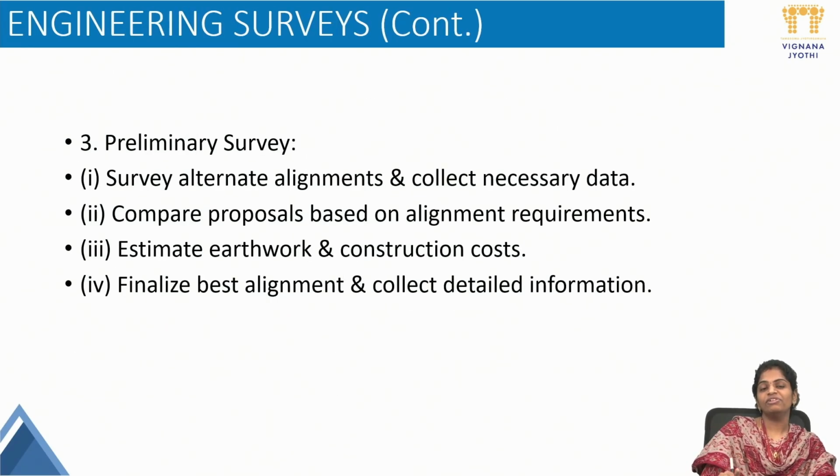In the third stage, we will go for a preliminary survey. Preliminary survey: alternate alignments and collect necessary data. Compare proposals based on alignment requirements. In this stage we will decide different alternative alignments, collect all the necessary data, and we will decide one best alternative among all the alternatives.